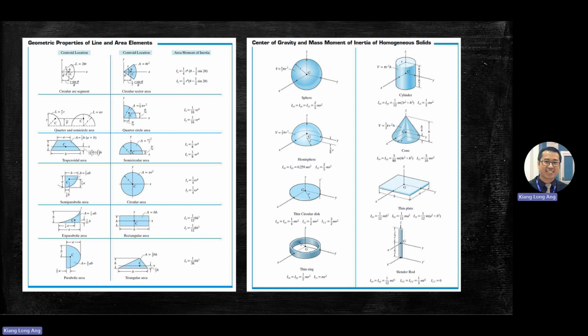So this one, you know that this is a rod. This is a rod, right? So for a rod, you use the bottom one. So I equals Ig plus MD square. The rod has its gravity, right? This is the G point, G1. This is G2, G2 for the disc.